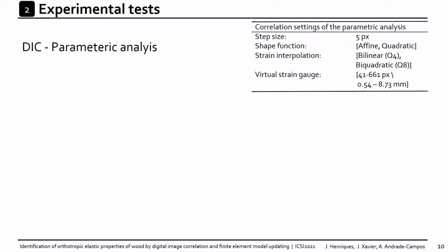The selection of the DIC setting parameters is a key topic when performing measurements through full field measurement techniques that influence the obtained results. This selection was carried out using the performance analysis module from MatchID software with a set of different parameter combinations in a total of 650 analyses.